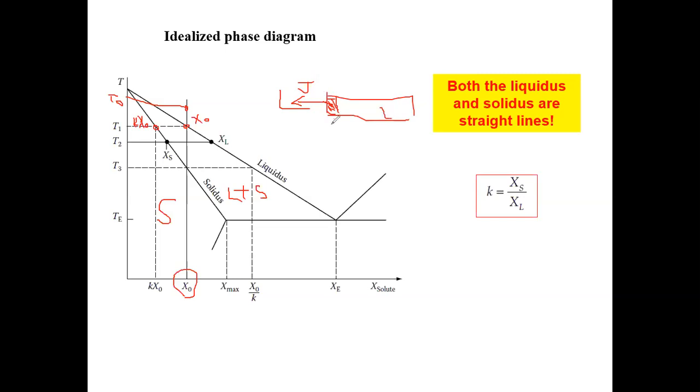This is my liquid, this is my solid. Suppose this is my solidification bar. If I only keep the temperature at T1, is the solid phase going to grow? If I have iced water and keep the water at 0 degrees Celsius, is the ice going to grow? No, right? Because this is the equilibrium temperature for this amount of solid and this amount of liquid, right?